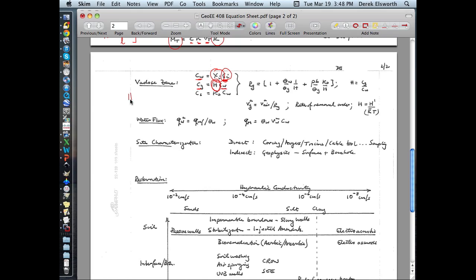The rate of transport through the gas phase was given by a retardation coefficient, which was in terms of the amount of absorption onto the solid phase through the water and the amount of absorption into the water from the gas phase, which gave the delay rate, if you like, of the velocity by diffusion or advection in the system. So in other words, if you know the advective velocity of vapor flow and you know the gaseous retardation coefficient, then the effective velocity at which those contaminants will travel is just the advective velocity divided by the gaseous retardation coefficient.